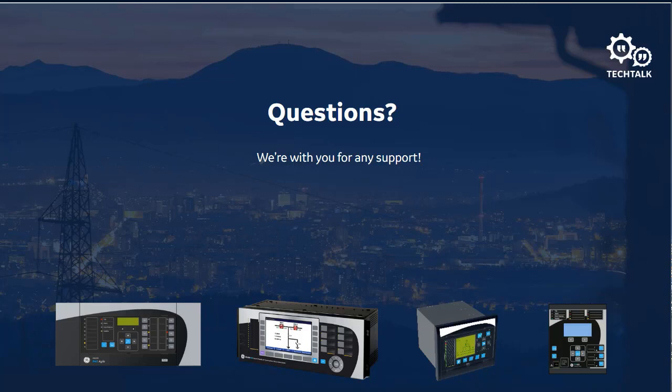The reason that we don't have line current differentials on every single transmission line out there is because we've only recently, and here I'm referring to us as a species, had the communications for line differential. Lines that were built in the time frame when communications didn't exist for that, or we didn't have the communications that exist today. So a lot of those transmission lines that are out there don't have those communications.